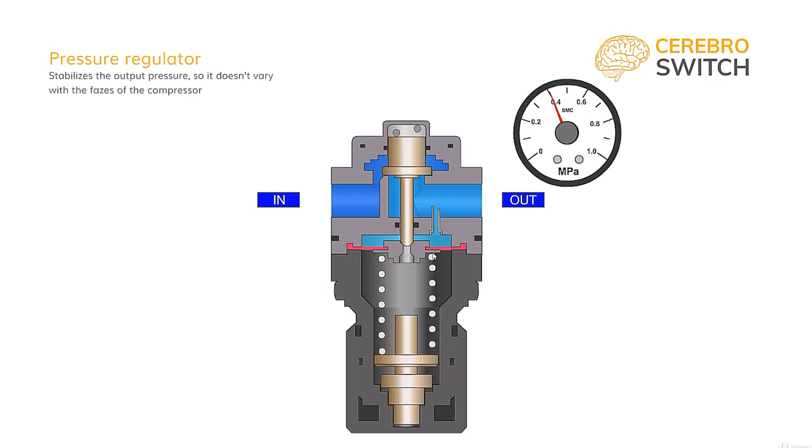Right now, the force of the spring and the force of the pressure on the membrane are balanced. If consumption starts and cylinders actuate, the pressure lowers. Think of it like there is a small bleed hole in the imaginary tank on the right. Then, the pressure force on the membrane lowers and the spring can push on the rigid disc to open the valve. This opening will balance at a certain point in such a way that it keeps the pressure steady at